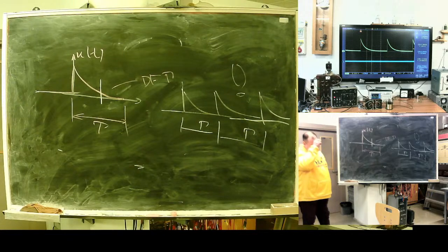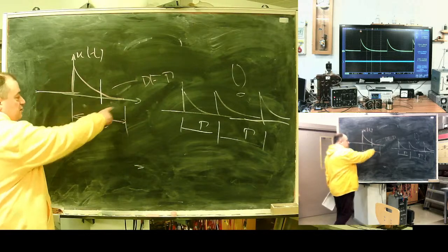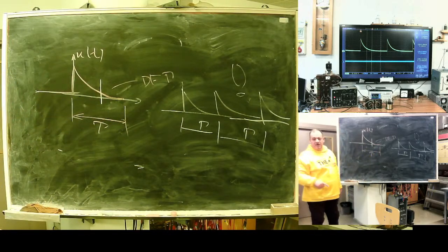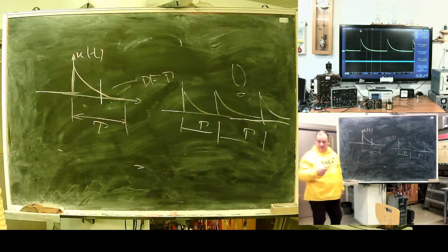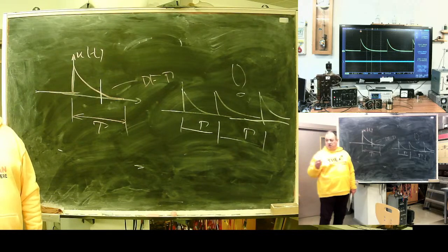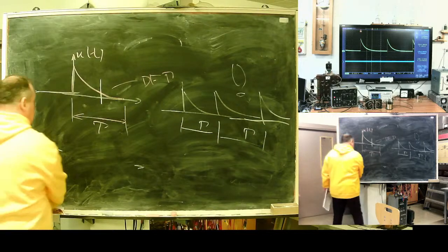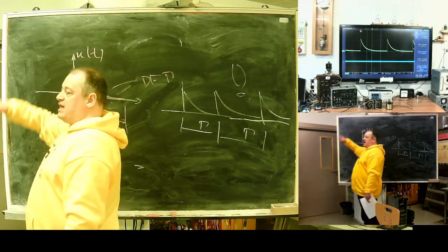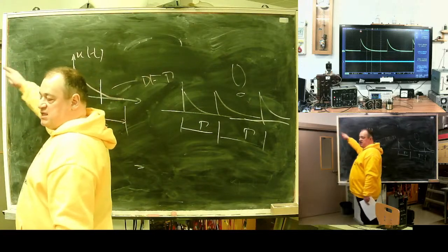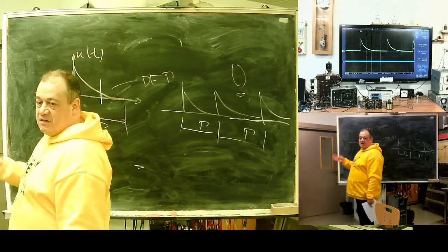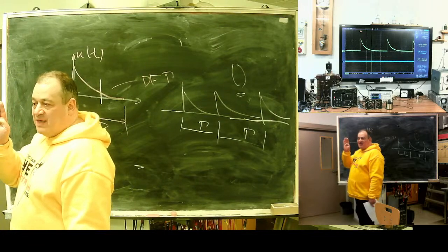Because for such, how to say, regular decaying, easy foreseeable signals, it will work. But if, for example, you try this for PWM converter, there is PWM. Modern electronics, modern power electronics, often has a spectrum like sine x divided by x. It goes with wave. And cutting simulation forcibly is dangerous.